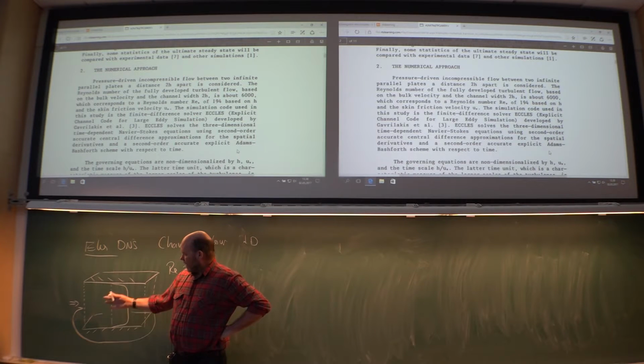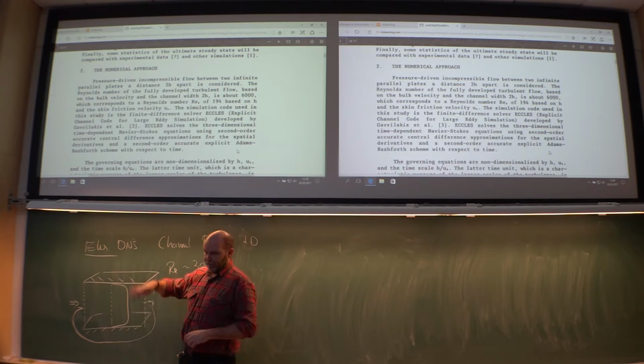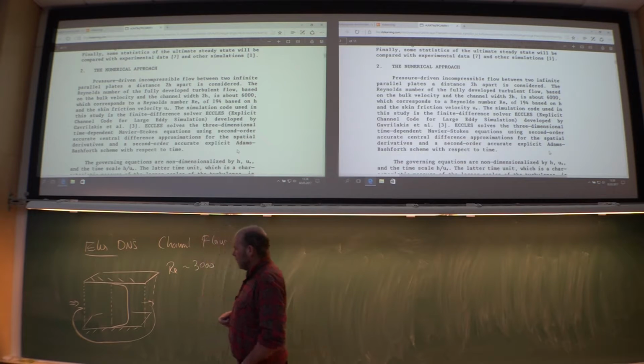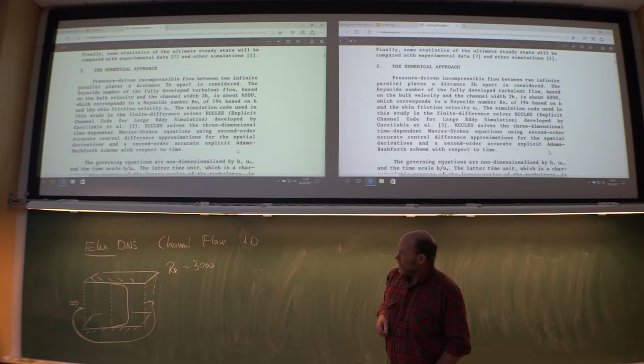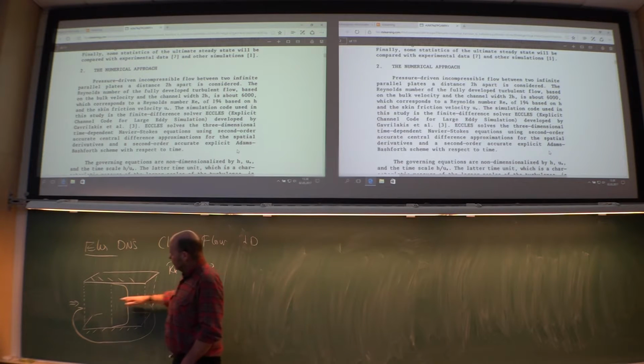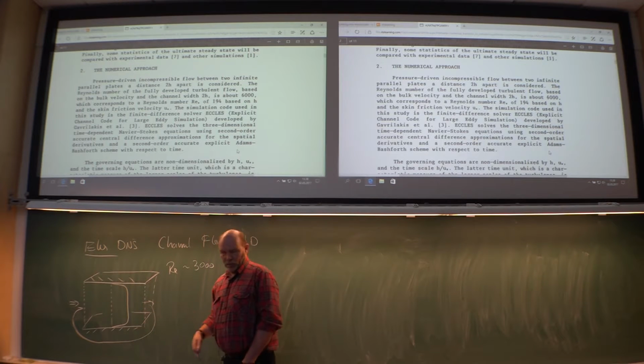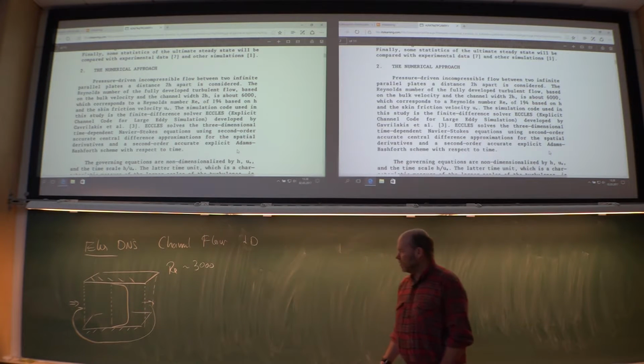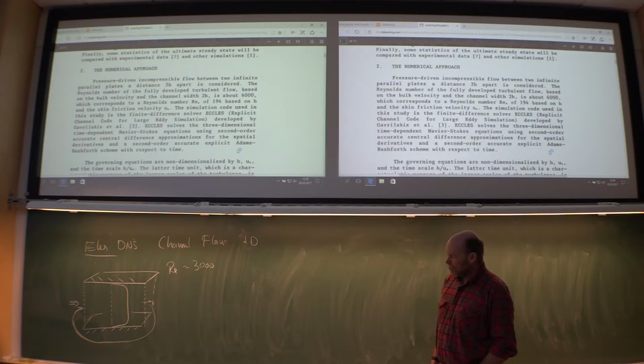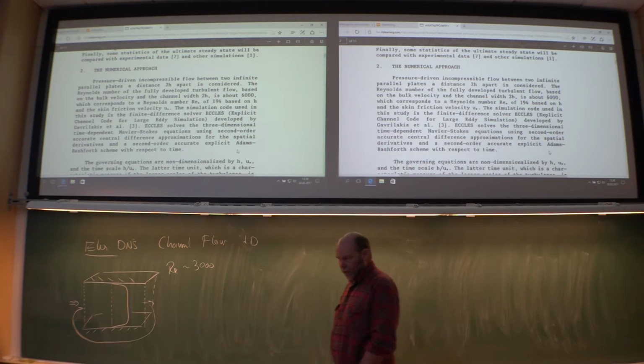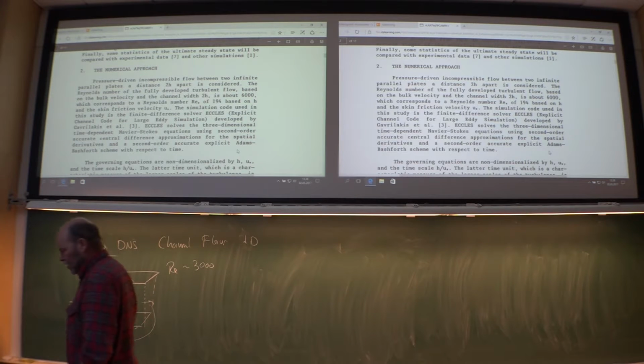So whatever comes out here, you send in on the other side, and vice versa. Sort of a cross-coupling there. So cyclic boundary conditions in both the streamwise and the spanwise direction. The normal direction, there you have solid walls, so not a problem there with any boundary conditions. And then you start to simulate. And you have a transient full three-dimensional simulation.